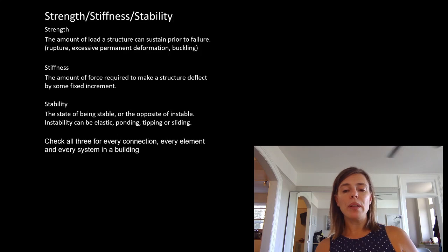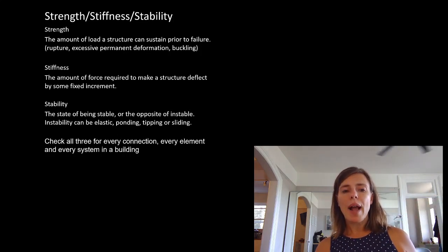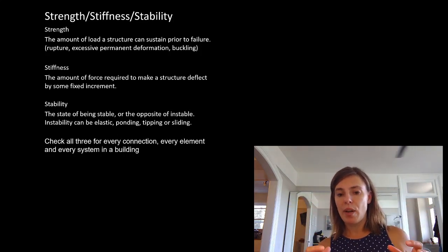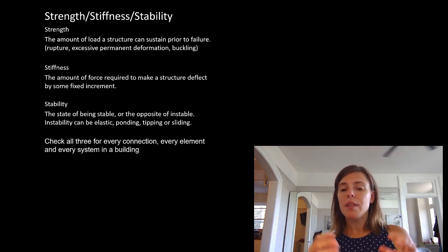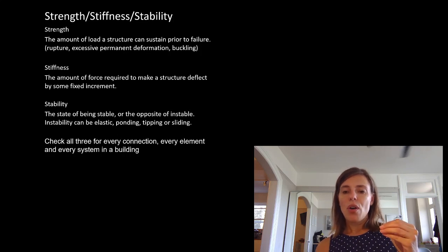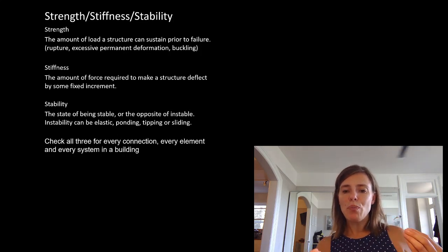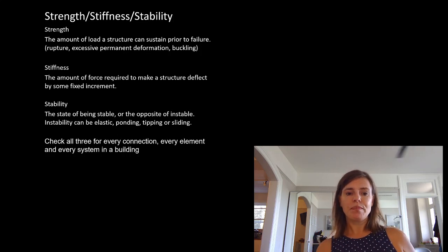And in fact, when you build your models for your studio classes, I always recommend to think about stability. If you have to stick it in too much styrofoam to make it work, it's probably not stable, unless you are going to do that concept in the ground to make it stable. If you need too much glue in a spot, that's a moment connection, which is a difficult thing to design. So you can usually tell by how you build the model where your trouble parts are in your actual structure.